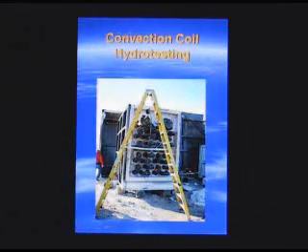This shows that plate we looked at before with the holes in it. This shows the tubes going back and forth through that. They're manifolded on the outside. This is called the turnaround compartment. It looks from the picture here, they're doing a hydro test on it with these lines coming down.